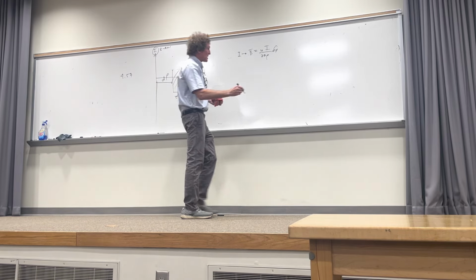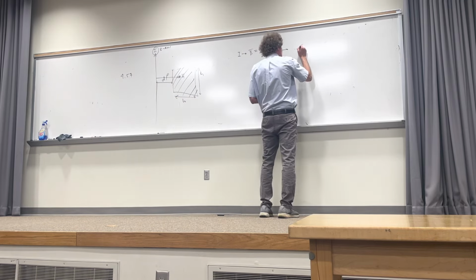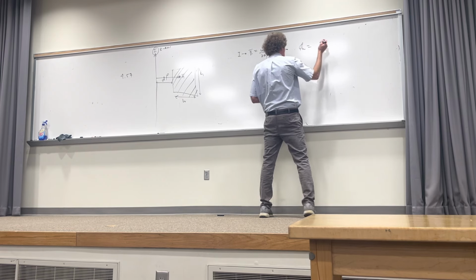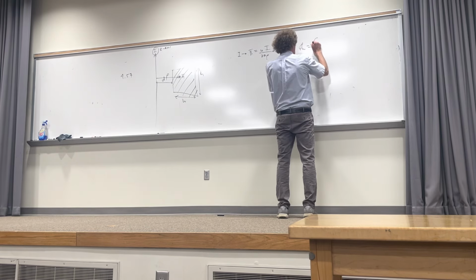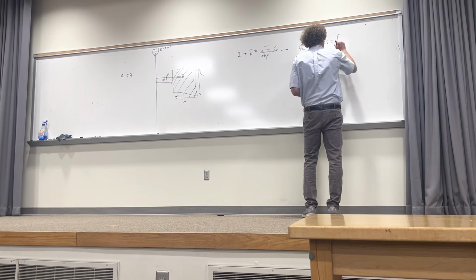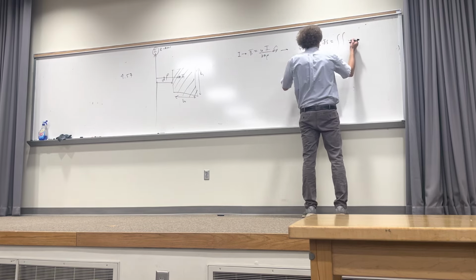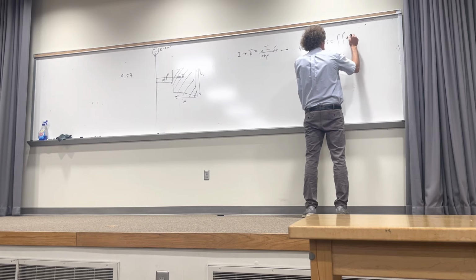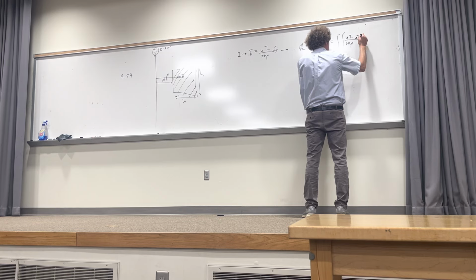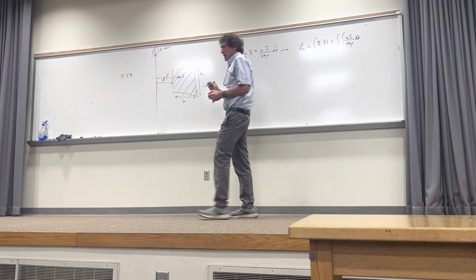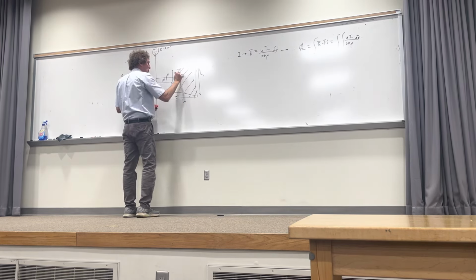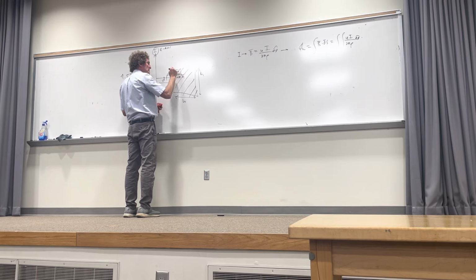So now I need a magnetic flux penetrating that area, and that would be the integral of B dot ds over that surface. Technically, it's a double integral. It's B, mu I over 2 pi rho A phi dot ds. And I'll ask this, what would the differential surface be there, class?